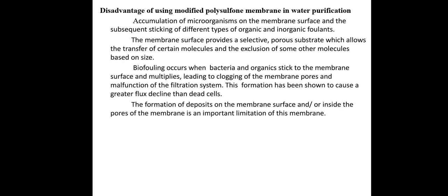Biofouling occurs when bacteria and organics stick to the membrane surface and multiply, leading to clogging of the membrane pores and malfunction of the filtration system. This formation has been shown to cause a greater flux decline than dead cells. The formation of deposits on the membrane surface and or inside the pores of the membrane is an important limitation of this membrane.